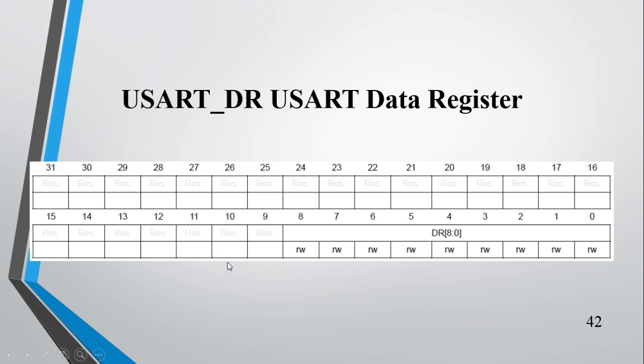So this is a data register which is used for both reception as well as transmission. There are only 8 bits because we can perform only 8-bit data transmission or reception using UART. So this is how you are performing the configuration of UART peripheral.